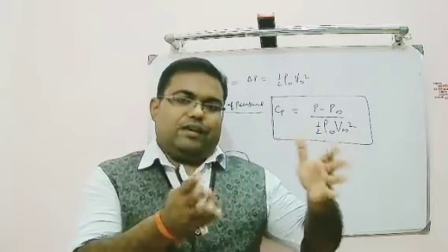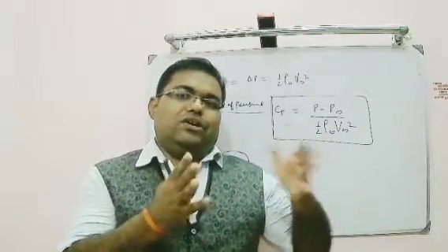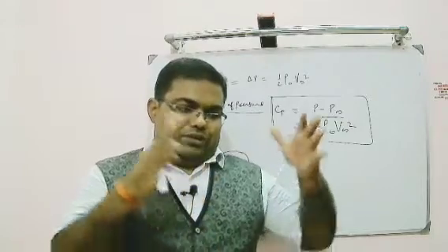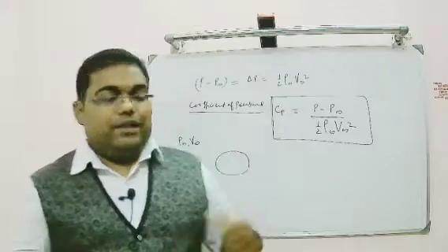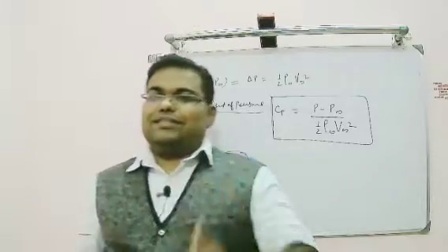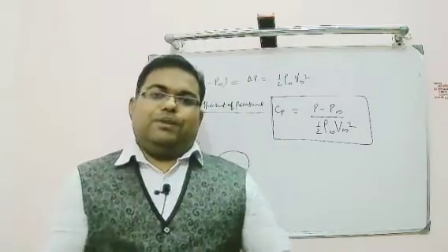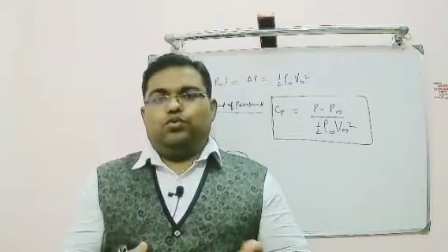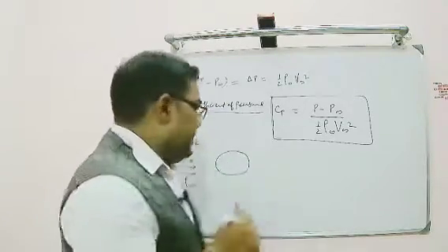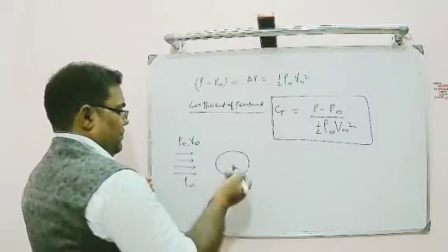The area or domain where we are maintaining the controlled atmospheric properties is known as the test section of the tunnel. So usually we mount this on the test section of the tunnel, and over the surface we put n number of static pressure ports. How will you do that? We will divide this surface into n number of points.